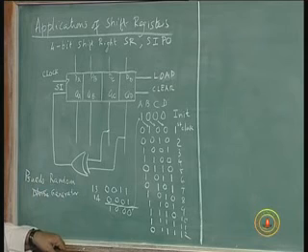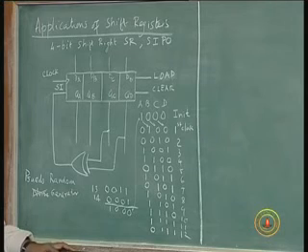What I mean is, suppose you want to have a verification pattern. You put in a bit pattern which is accepted, and for that bit pattern you know the sequence it has to produce. So you can know whether there is any error in the transmission, if you agree on the initial pattern, both the sending and the receiving end.